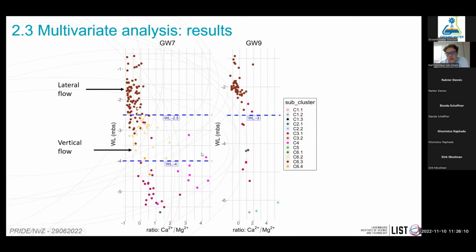So what happens is that on the plateau, you have sort of a quasi perched aquifer situation. You have this weathered material that's sitting on top of a semi-leaky or fractured slate that is quite dense. If the water level goes up to a certain elevation, and it exceeds the line where the weathering front stops on the slope, this water spills over onto the slope, and it runs, and it's practically not chemically altered at all.